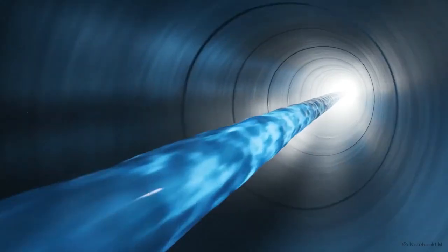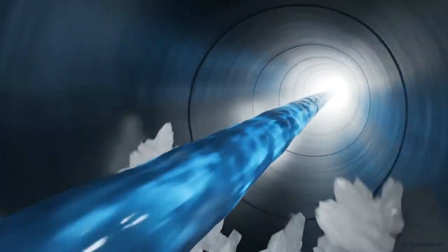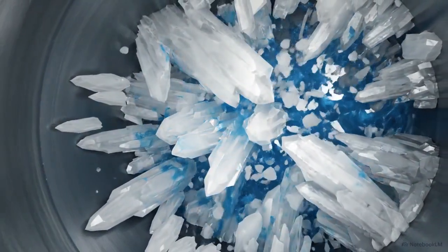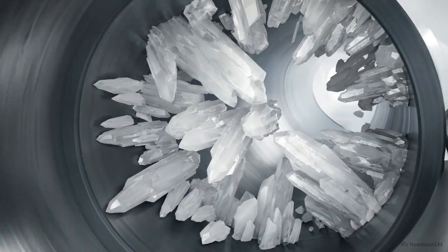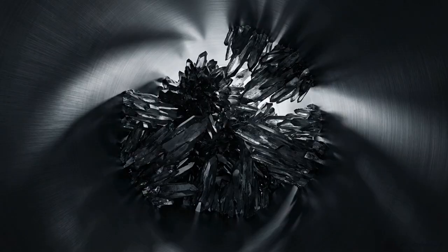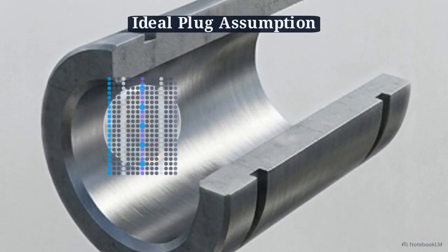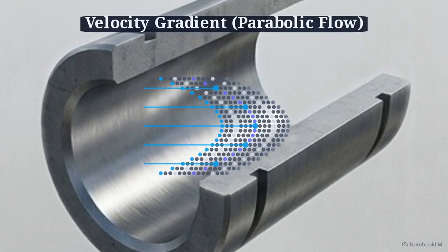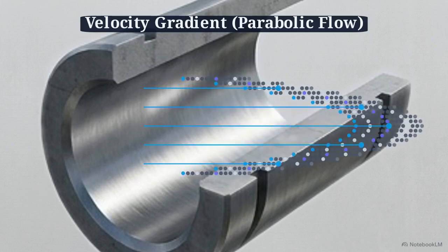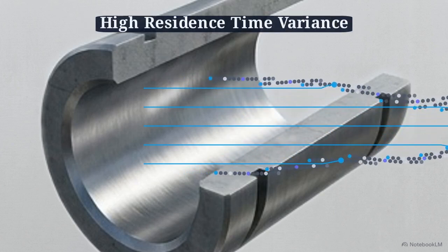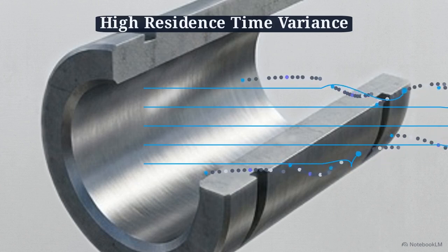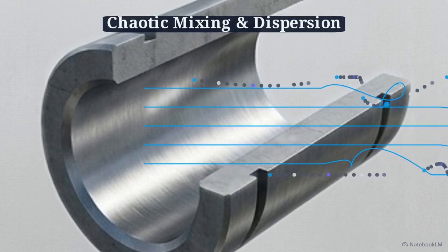When that flowing stream suddenly thickens or crystallizes, the ideal physical model rapidly collapses. This reveals the system's primary weakness. Plug flow reactors are notoriously difficult to operate when handling solid-forming reactions that can easily pile up and obstruct the continuous narrow pathway. Highly viscous reactions pose a similar threat. If thick fluid adheres to the reactor walls while the center continues to move quickly, the entire plug assumption breaks down, resulting in wildly unpredictable residence times for different parts of the mixture.